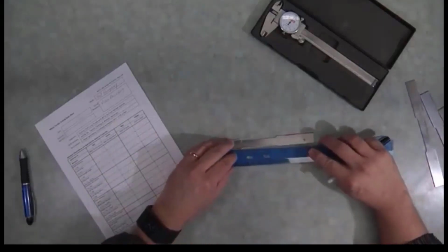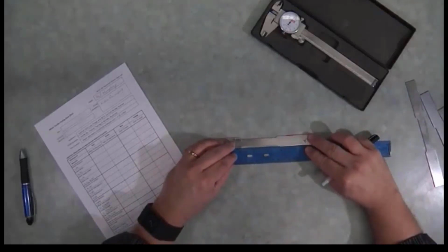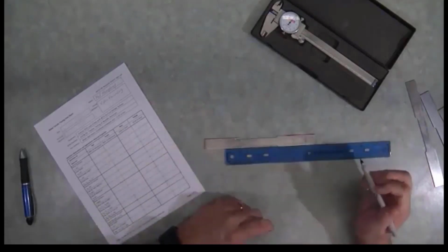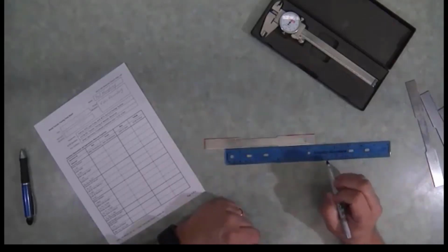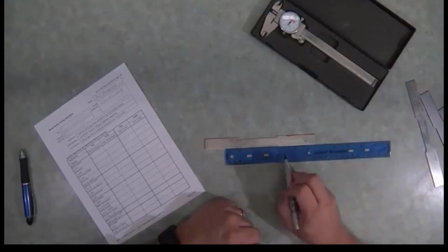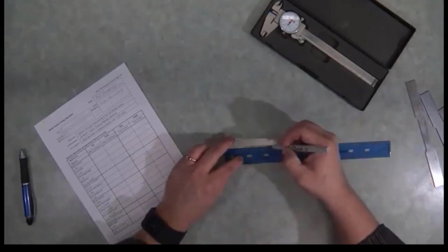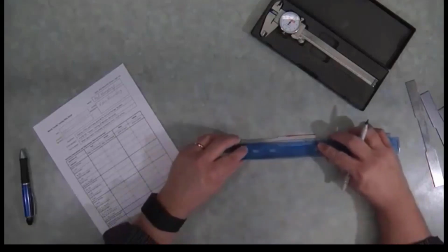So we'll push these aside, and I'm going to measure from the corners of the test section here rather than from the end of the whole specimen, because it is possible that the test section is not perfectly centered, and we don't need to be absolutely precise about this. We just need to be pretty close. So we've got 2 3/4 inches, so half of that is 1 3/8, which puts me right here. So now I'll measure 1 inch to either side of that.